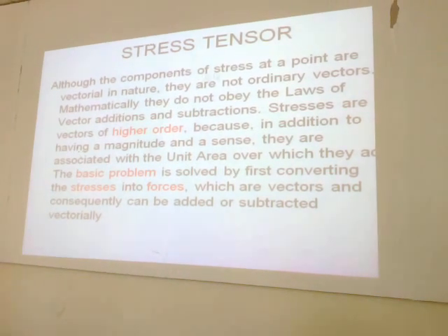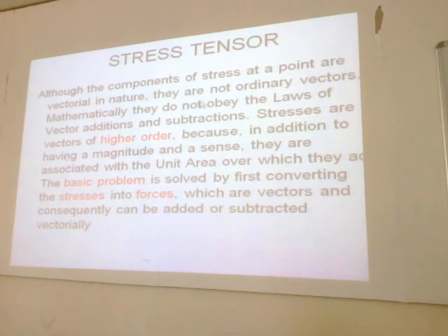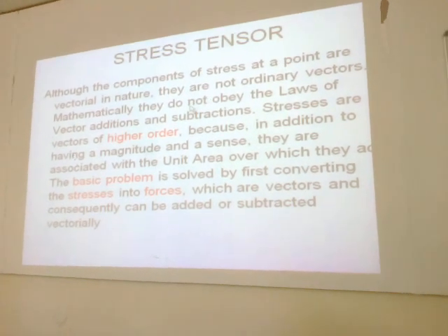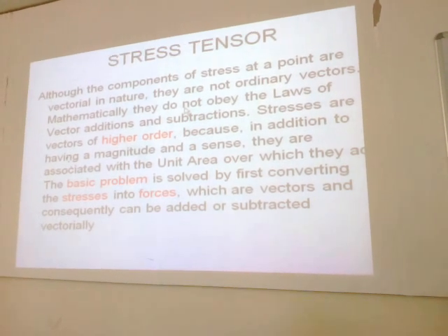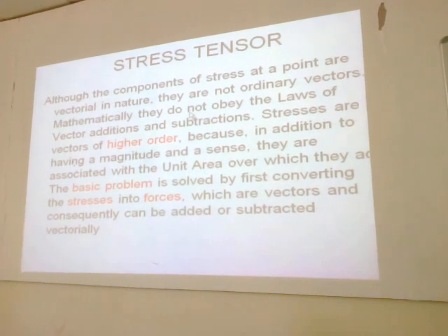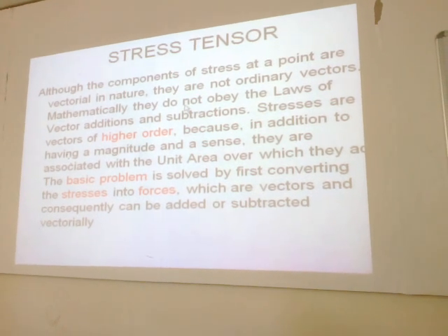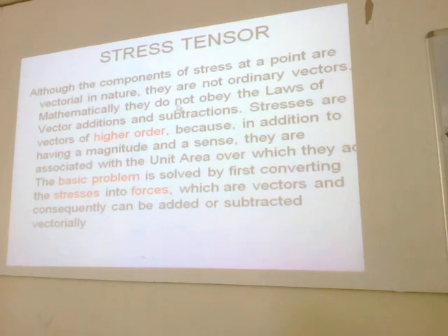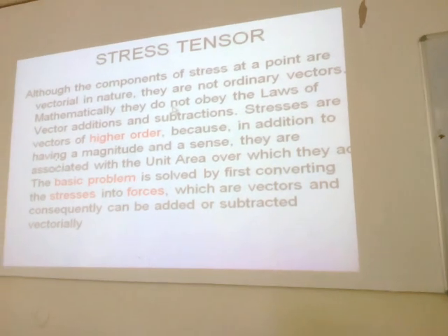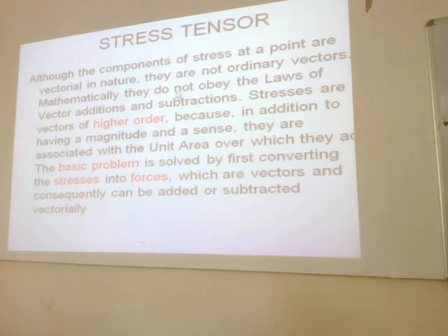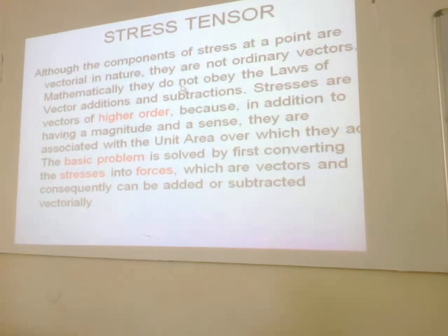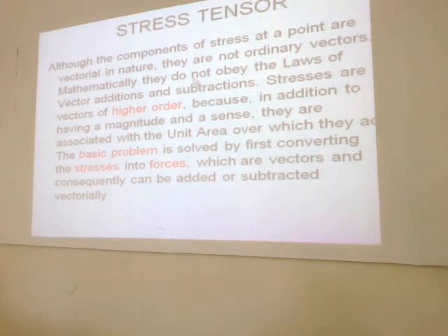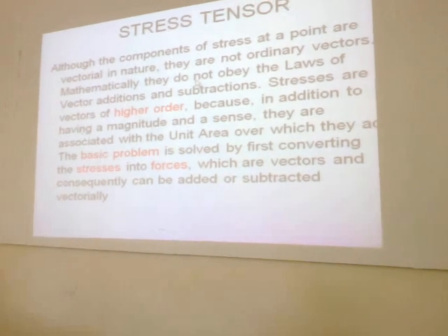Although the components of stress at a point are vectorial in nature, they are not ordinary vectors. Mathematically, they do not obey the laws of vector addition and subtraction. These stresses are vectors of higher order because, in addition to having a magnitude and sense, they are associated with unit area. As you change the plane, you have seen normal and shear stress having infinite combinations.